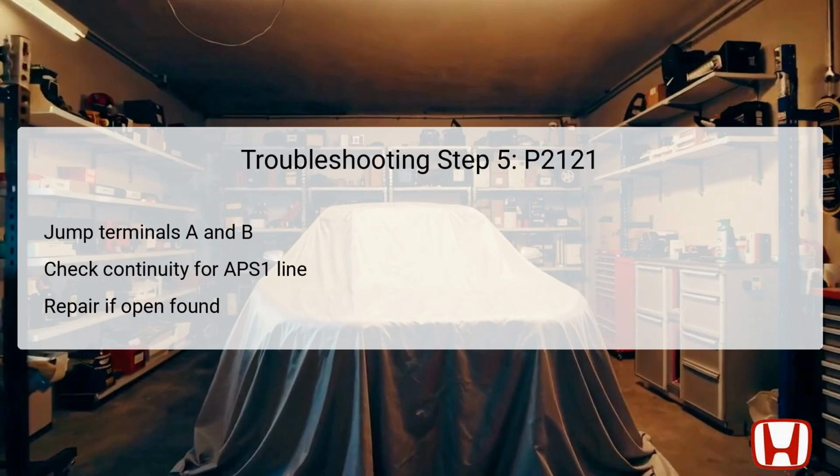If no continuity is detected, this indicates an open circuit in the APS1 wire that needs to be repaired, as it is essential for the APP sensor's proper operation and ensuring accurate readings are sent to the PCM.